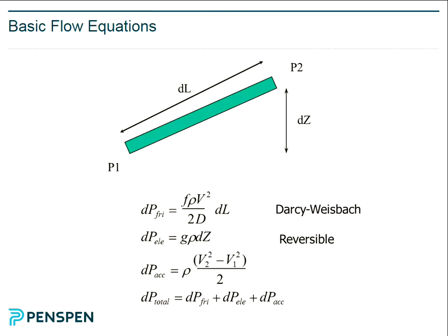So the friction factor, that's the term. Basically our pressure drop is proportional to the friction factor. And the friction factor is a function of the Reynolds number, the roughness and the diameter. And the Reynolds number is a dimensionless group, which is typically a very high number for a fluid in a pipeline. So it's a relationship between the density and the kinematic viscosity, basically.